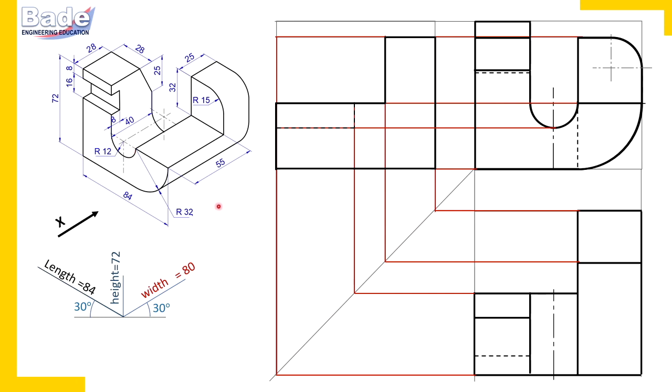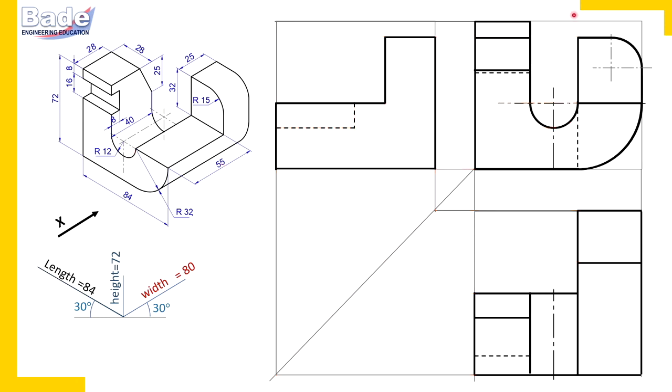This semicircular slot is hidden from the right side. From the top there is nothing to hide that semicircular slot. So watch here, that semicircular slot is visible, but here that semicircular slot is hidden. Okay, now we'll focus on this surface.